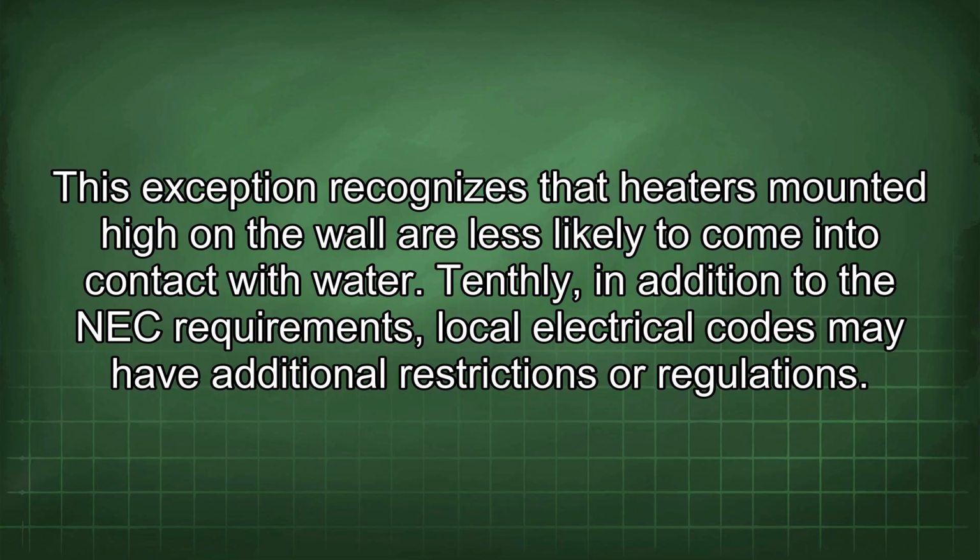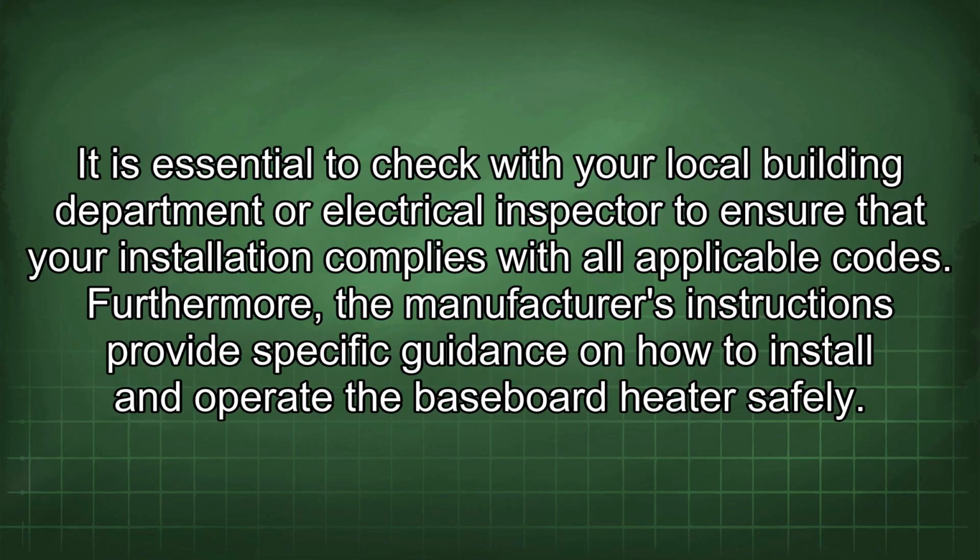Tenthly, in addition to the NEC requirements, local electrical codes may have additional restrictions or regulations. It is essential to check with your local building department or electrical inspector to ensure that your installation complies with all applicable codes. Furthermore, the manufacturer's instructions provide specific guidance on how to install and operate the baseboard heater safely.